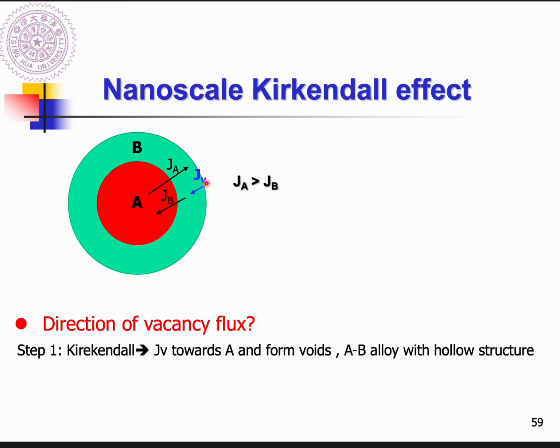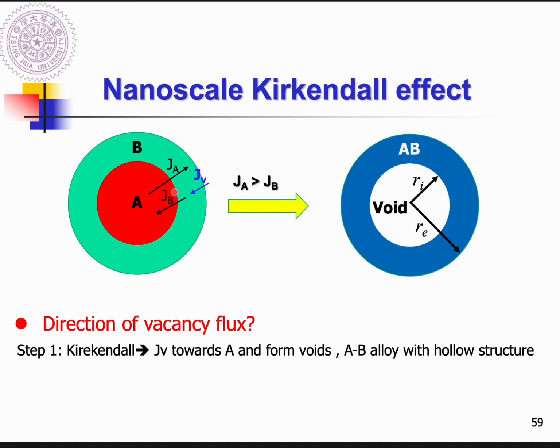The vacancies will move toward the inside, and the vacancies will accumulate in material A. After a while, as the diffusion continues, because the voids in the beginning are small, small voids will aggregate and form a large void.